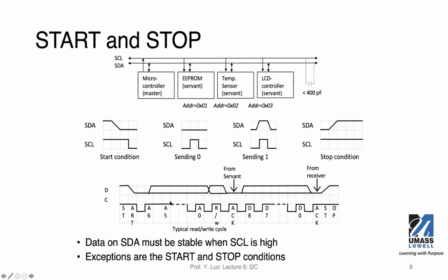And you notice that this is again the timing diagram. You see these double lines in parallel, indicating the data is valid. Here we use A6, A5, to A0. We have 7 bits here. These 7 bits represent the address of the target IC that the sender is trying to communicate to. So whoever has that address should respond.